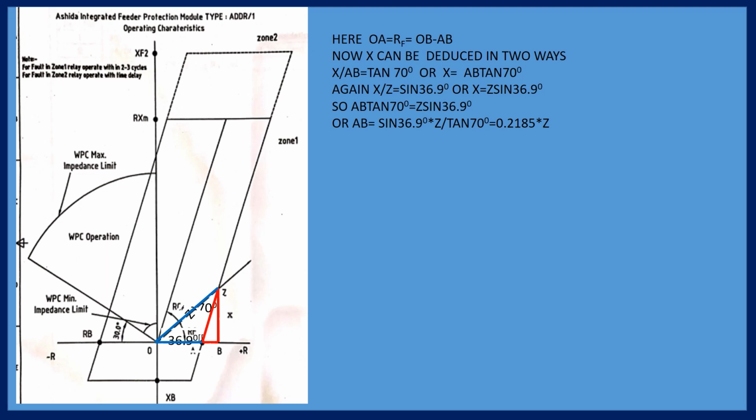Next is the sectioning point. Each sectioning point, if you don't earth separately by two discharge rods in each section, you may get shock. Sometimes, suppose on one side there is a section insulator, and the other section has an isolator switch.